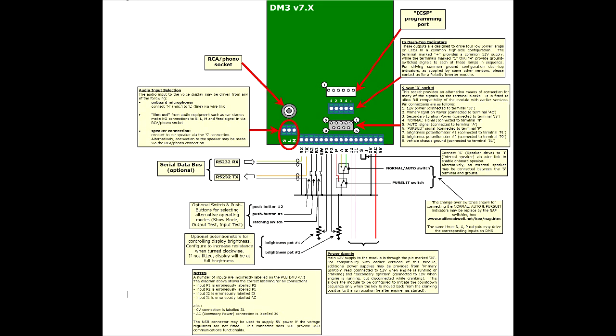You'll see that audio input can be taken through the 3-pin connector marked terminals S, L and M. That's speaker input, line input or microphone input. We'll speak more about those in the video which follows as to the actual connections. The speaker input is very seldom used. It's just like an alternative for an audio input that goes through the phono plug.